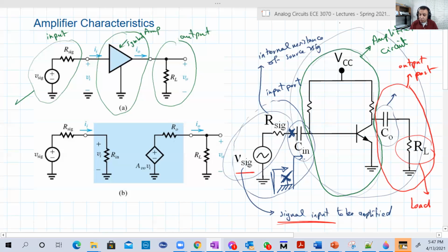But remember, now this is AC. We want the AC analysis. So in AC, we're going to ignore VCC, which is a voltage source. I'm going to prove for you in the next video that we should ignore VCC when we talk about AC, the amplification stuff. So if we look here, we're going to see a circuit with no AC sources, only resistors.